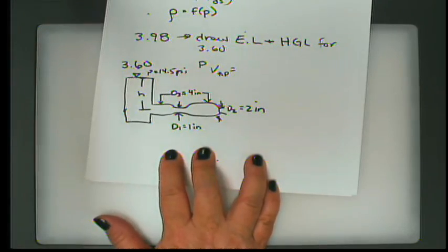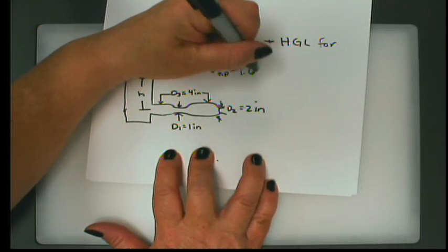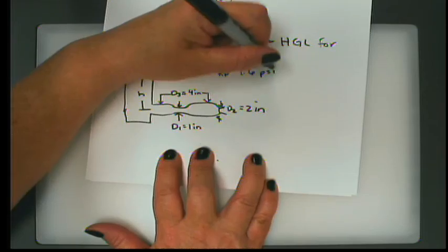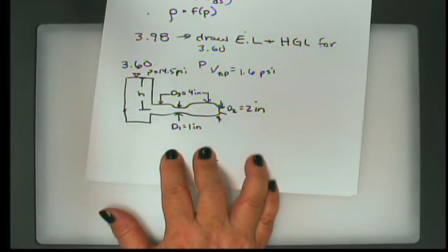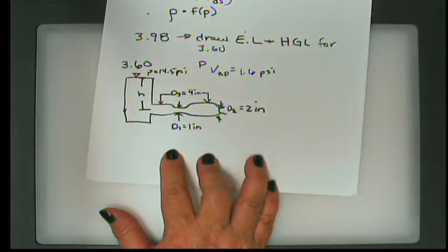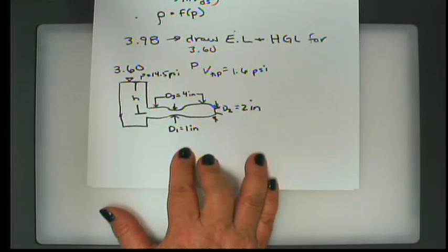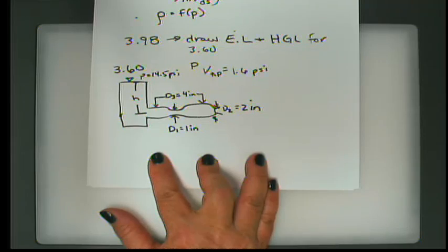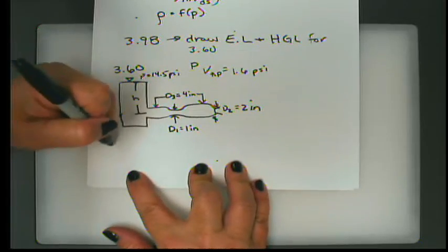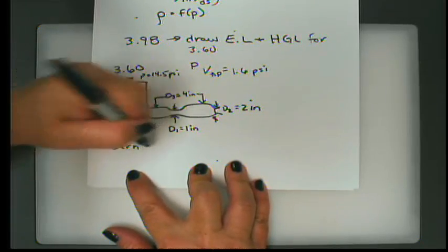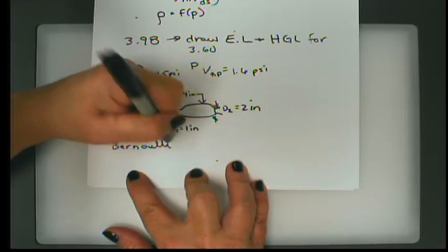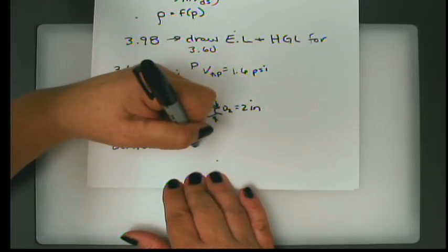Okay, so I am further told that the vapor pressure is 1.6 psi, or psia. So I'm going to neglect my viscous effects. We're talking about water, and we don't have a pump. We're going to assume no line loss. So we can say then that the Bernoulli equation is applicable in its unadulterated form.